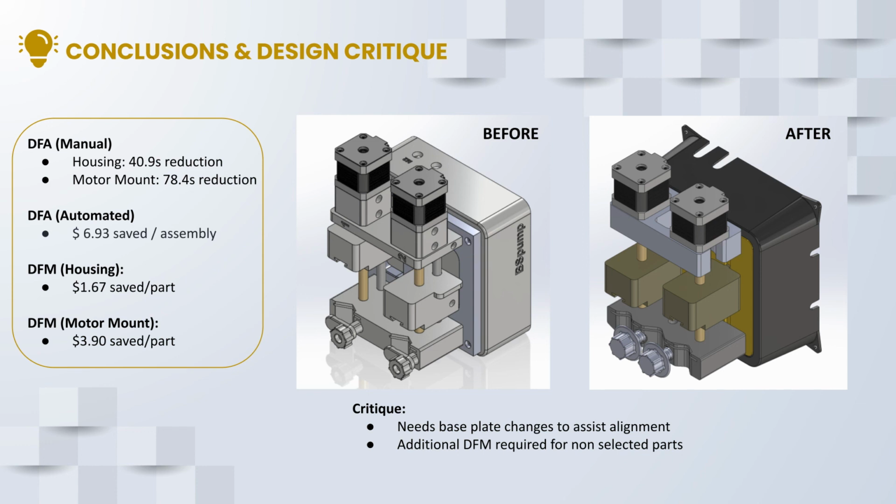To summarize, after redesign, we were able to significantly reduce manual assembly time of the housing and motor mount. We cut down automated assembly costs of the bottom bracket and syringe mounting system, and implemented DfM guidelines to improve manufacturability and reduce the manufacturing cost of the machined motor mount and injection molded housing.